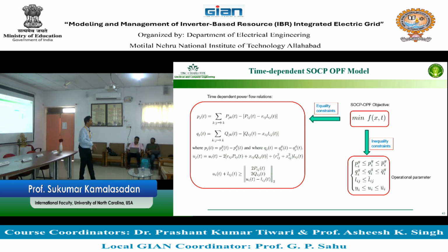So to run the power flow multiple times, what do you have to do? You have to get some information from the grid, then run the power flow. If this information is the same every time, morning, afternoon, then there is no point in running it. So can you tell me what information you need to run the power flow on the electric grid? Load values. These are no-brainer. Load changes with respect to time, so you have to collect the load value.